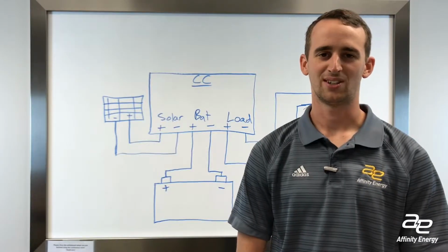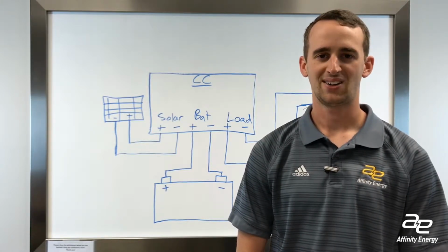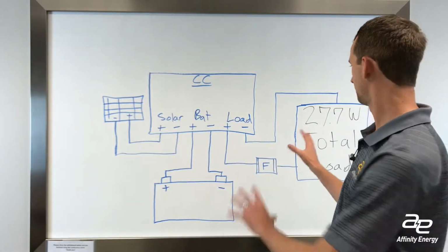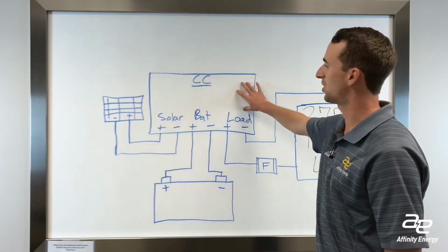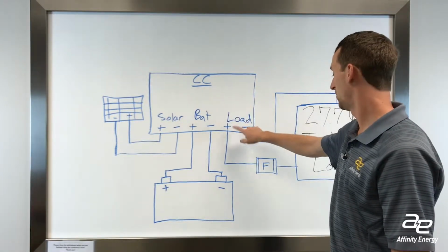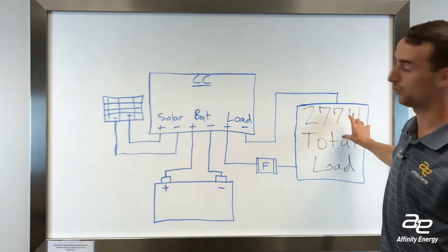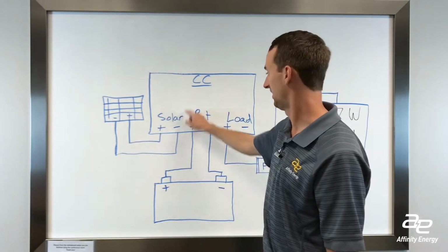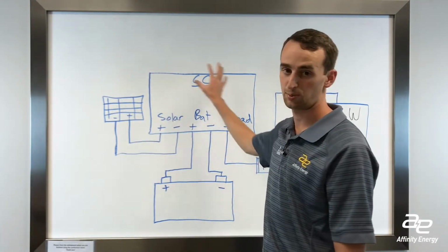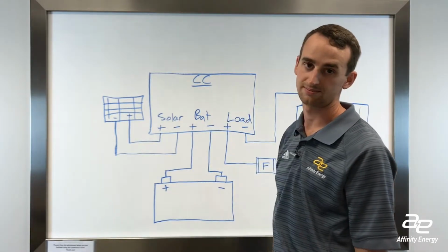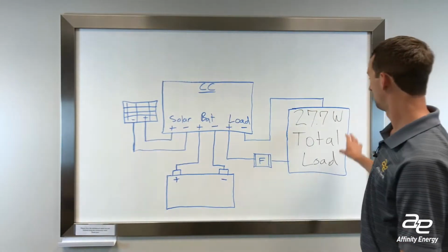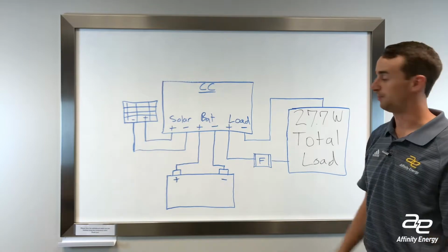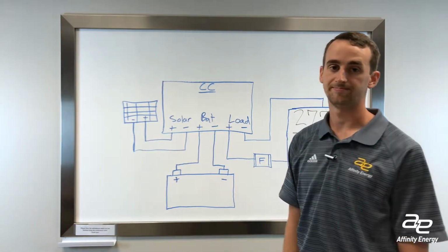The third factor for our design that we need to consider is the battery, the solar module, and the charge controller. So you can see up here I've got a rudimentary drawing. So this is the charge controller here, and then the load, this is what we calculated before, is the load of our devices here, and then you've got a battery connection here, and then the solar panel connects here. So this is pretty typical of all charge controllers. So for our application, we've got a 24 volt DC load. And so the battery needs to be a 24 volt battery.